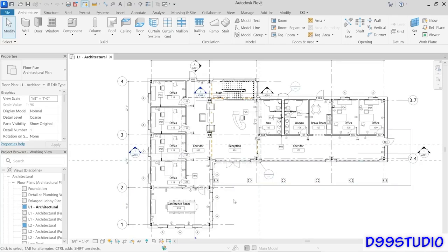But right now, this floor plan is showing some information that I really don't want to see in those documentation views. Now, assuming that you don't want to permanently eliminate some of the items that I'm going to share with you, then what you want to do is maintain a working view as well. Now, all a working view is another view of the model that you use to get your work done. So it is like a private view that you use for the day-to-day editing of the model that you don't share with outside recipients. And that's really all we mean by a working view.